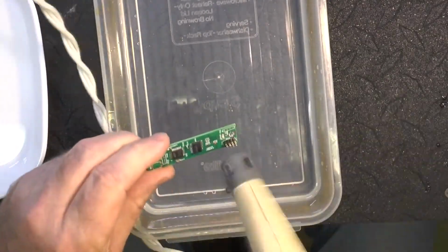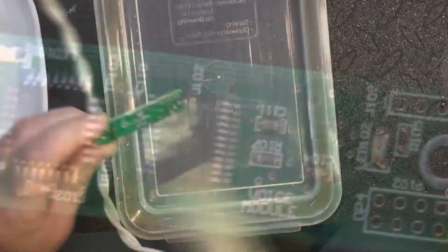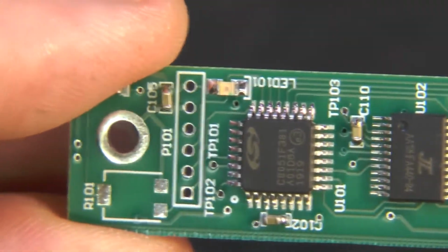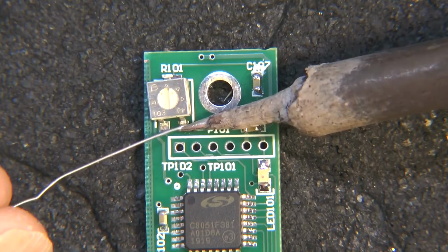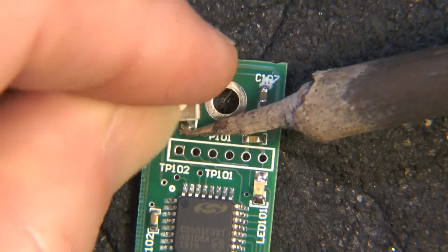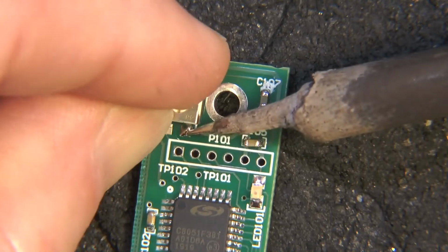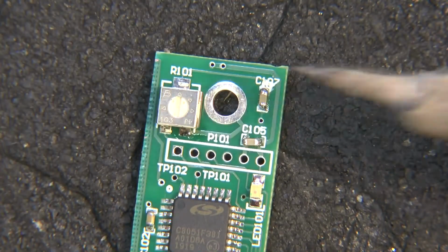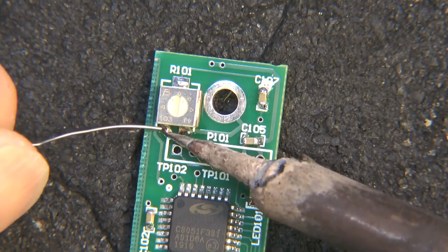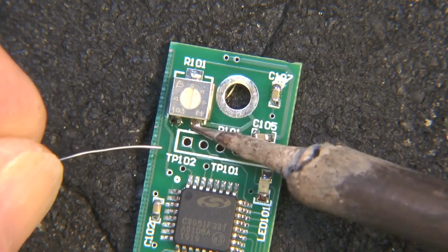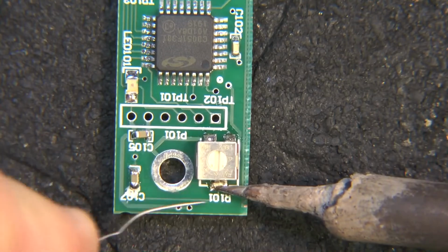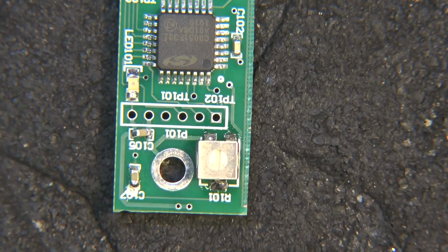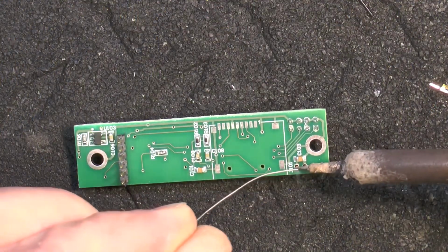And that gets most of the water out from underneath things, and then you get a nice clean board. Potentiometers, connectors and such you add later, because you don't want the alcohol and the water to get down inside of these parts. So those have to be added later, and the best you can do is take a swab of alcohol and clean it up with that.